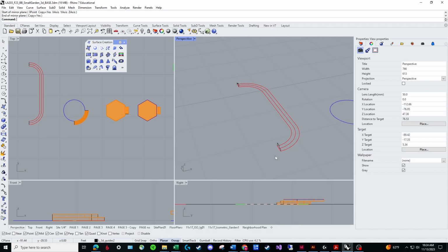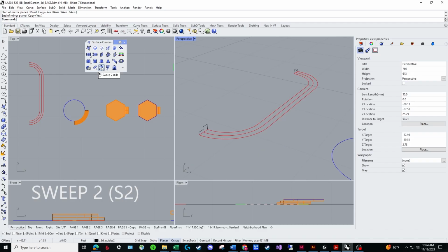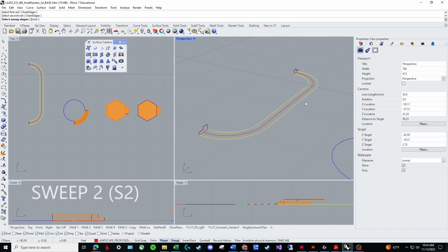It's exactly the same. Where this is really kind of cool, any sweeps will actually do, if I want it to be square and then tighten up or get wider and then come back to a narrower sort of look. So sweep 2 rails, I click. In this case, obviously there are 2 rails instead of 1. And then it wants to know my sweep shapes. So here are my sweep shapes.